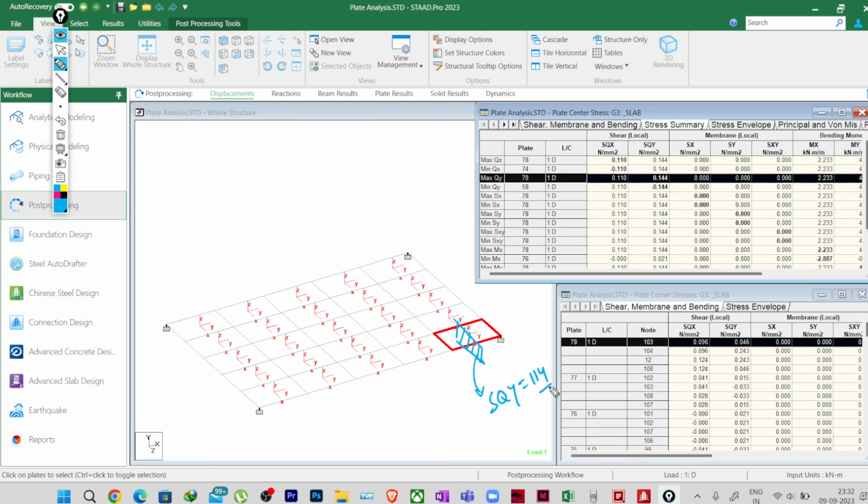Okay, so for this shear you will be finding Vu by bd, you will find the shear stress. So this is the shear stress it is giving. But here one thing you remember, STAAD is giving shear stress based on the total depth of the section. So you need to convert it for whatever depth you are designing, because ultimately you need the Vu, right?